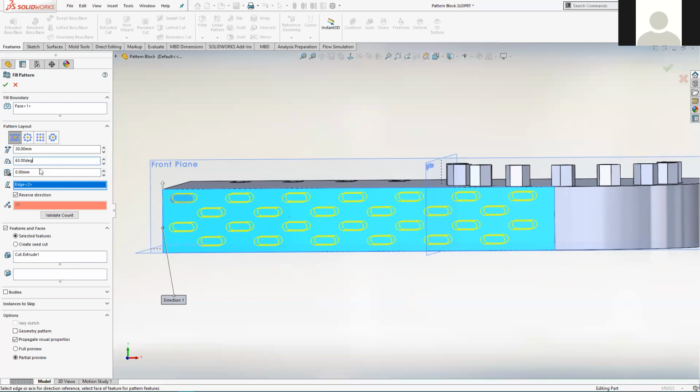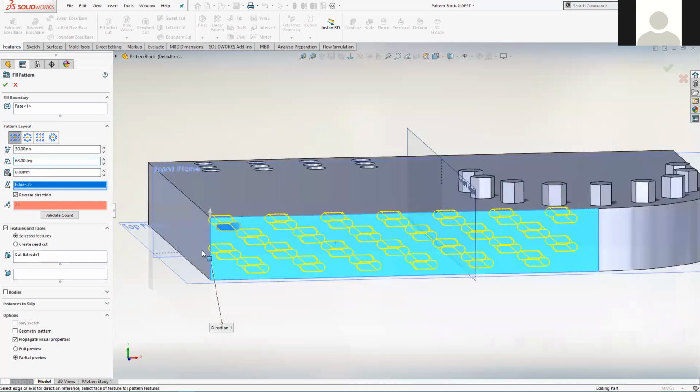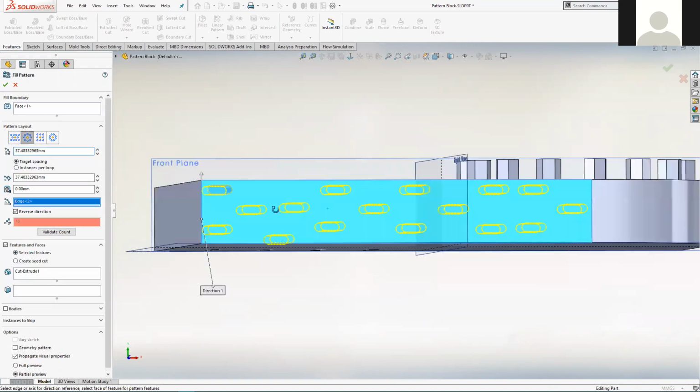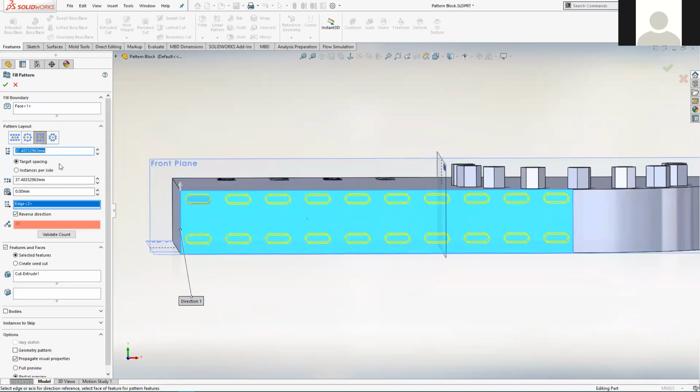You can play with that for a long, long time, but I have actually created laser cut meshwork stainless steel parts using that. So that's what it can be quite useful for. And used in combination with a hexagonal sketch cut or a hexagonal extruded cut, and with the right angular spacing, you can create hexagonal shapes, and you can create quite a nice grid work, quite a nice mesh work. But yeah, you have to kind of get a sense of what the settings are doing first. So there is a certain amount of play that you have to do in there to get the sense of what's actually going on.